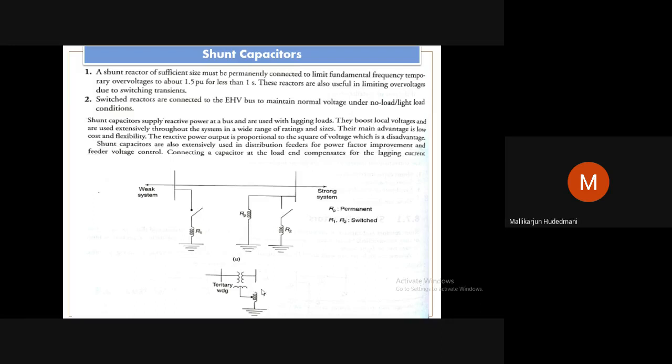So you might be aware of this. Whatever compensating devices are incorporated at the transformer or through the transformer are basically at the tertiary winding. Primary, secondary. Primary is the one which interfaces as an input, secondary is from where power is drawn out. The tertiary is the one which is left for the control of that. So therefore, this tertiary winding is equipped with controlling devices, either like an inductor, capacitor, or any devices which are going to compensate for the requirement like this.